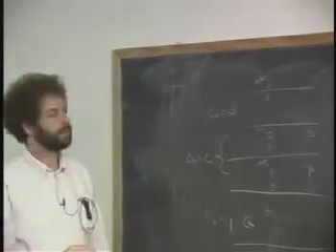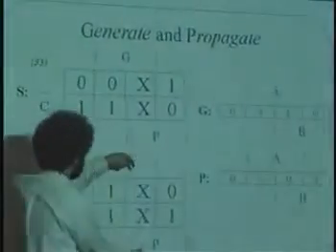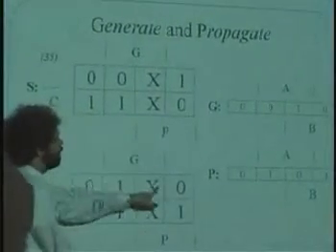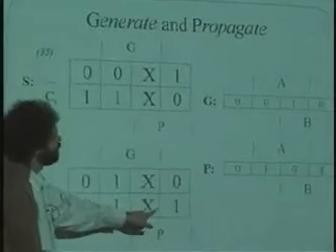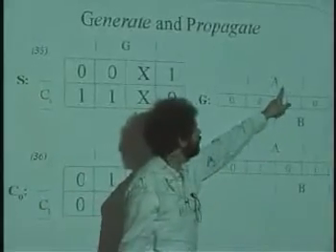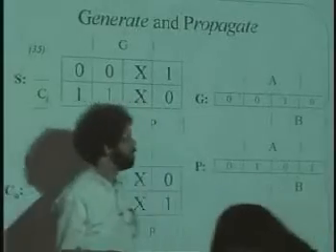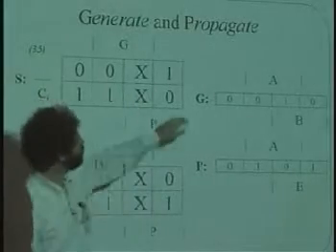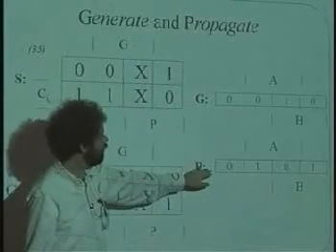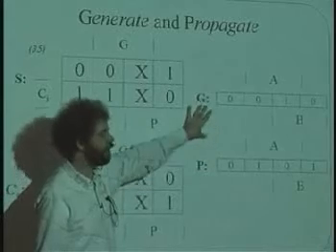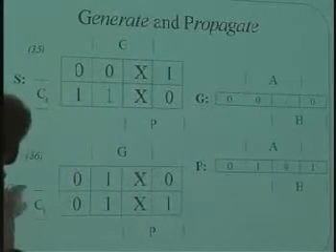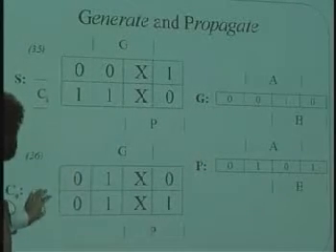Great. Nice. So, it will not be the case that generate and propagate are ever on at the same time, and that's the reason for the X's here, because we're saying that in the generate case, when A is high and B is high, we're going to turn the propagate off. So we're going to pre-compute G and P, and then based on G and P, we're then going to compute C sub O as a function of C sub I.